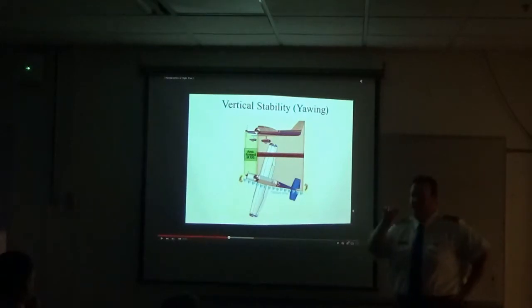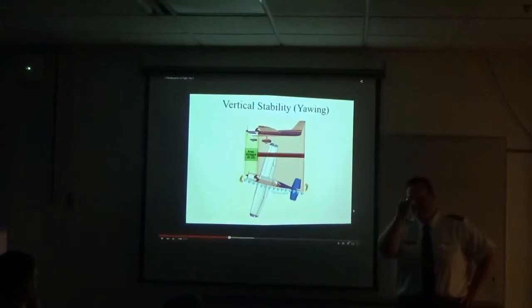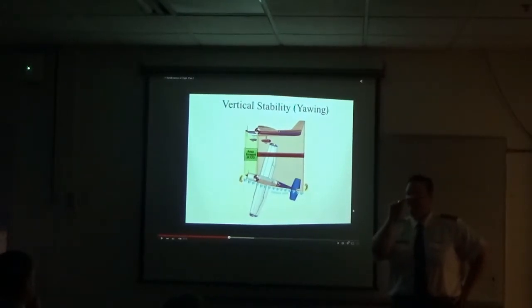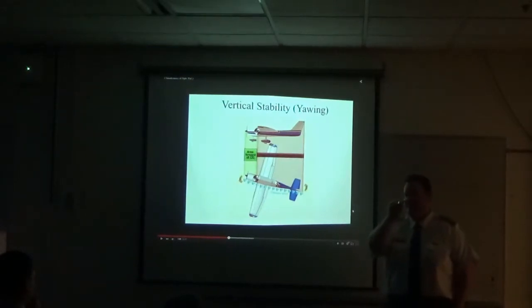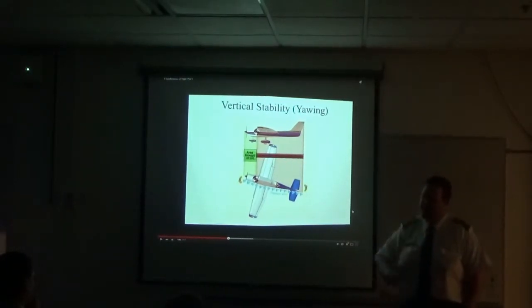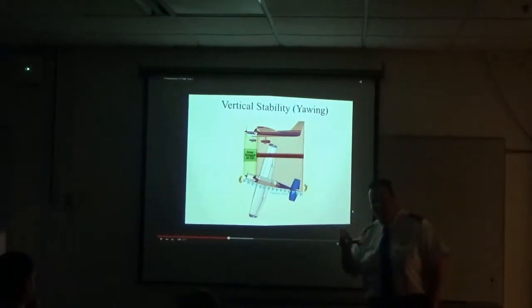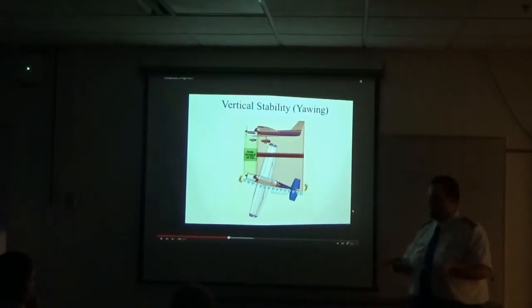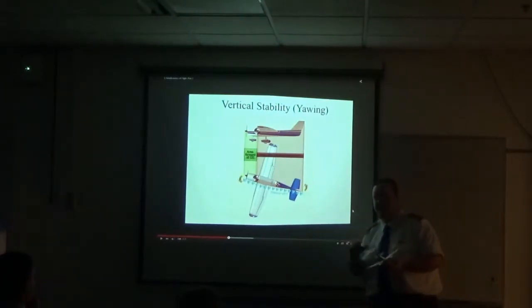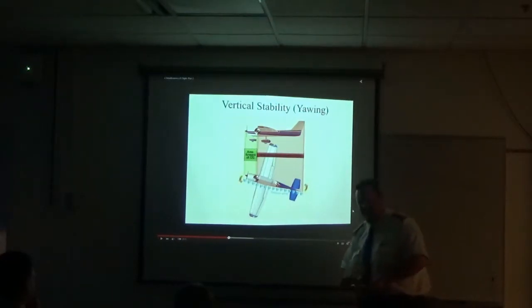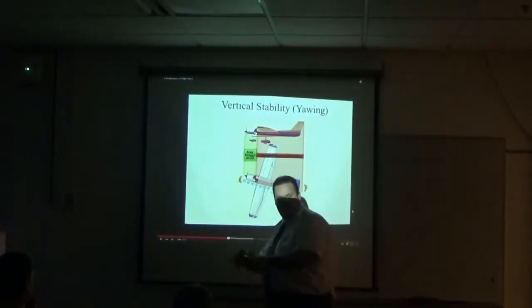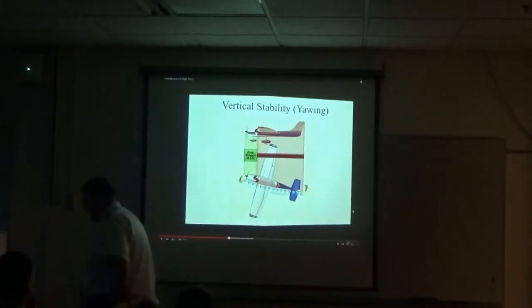You'll start to notice, in flight, if you're starting to get a distribution, because you'll kind of get that listing thing. And if you just check your fuel gauge and you see, oh wow, I had to switch over to this one for a while, you switch to the other tank, it'll eventually just equal itself out, because, as it was stated earlier, most trainer aircraft or small aircraft like this, or any kind of civilian ones, are usually positively stable. So once you correct the imbalance, it automatically fixes itself and goes back to stable flight. Any questions? All right.